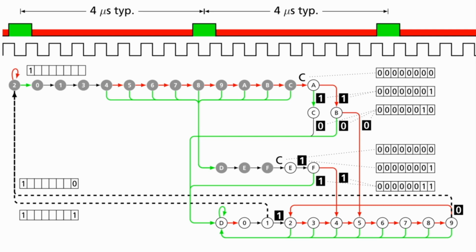All this cleverness around remembering the top 2 bits is to give the processor more time to realize a valid byte has been read. While all of this is going on, the processor is constantly asking the disk controller, do you have a byte? Do you have a byte? In any gray state, a valid byte is in the register for the processor to read. The complexity of what I've shown you here has mostly come from handling timing variations.